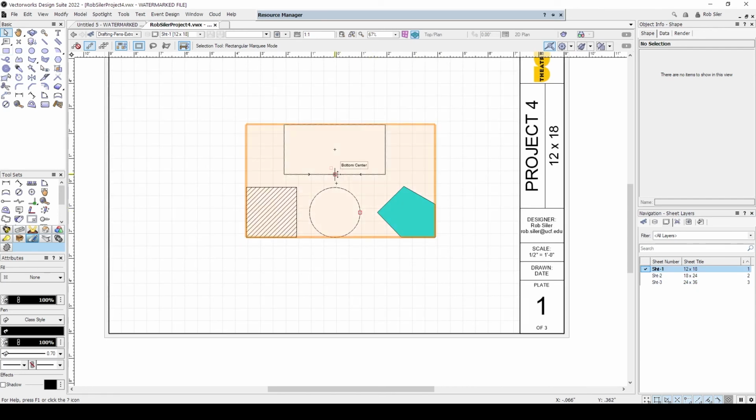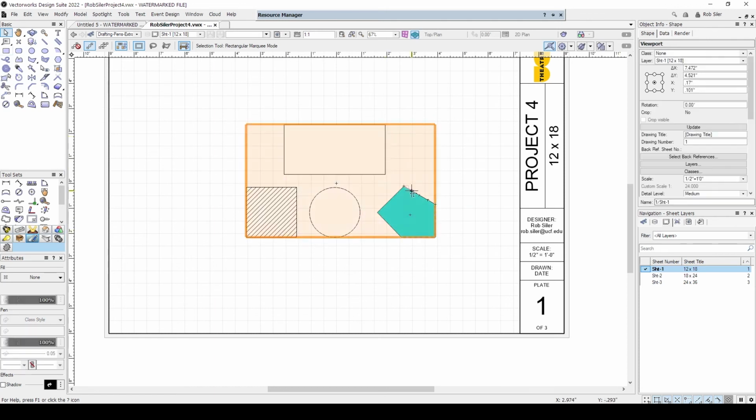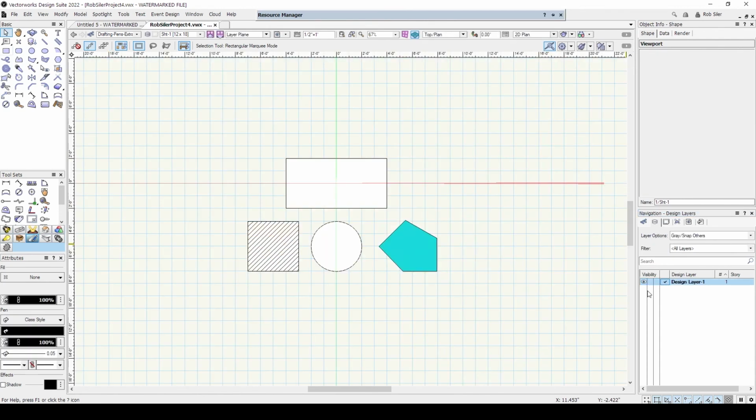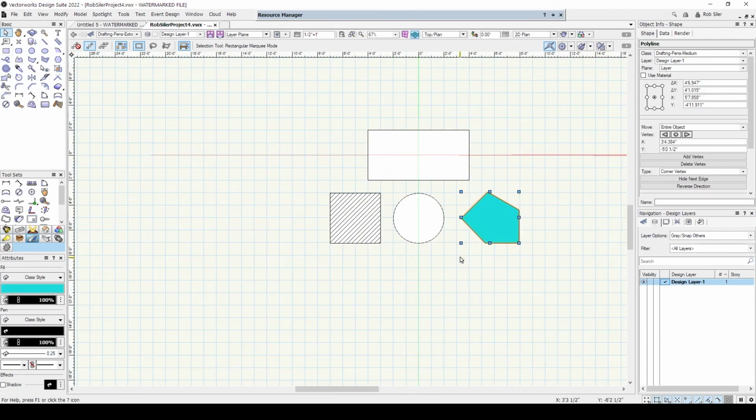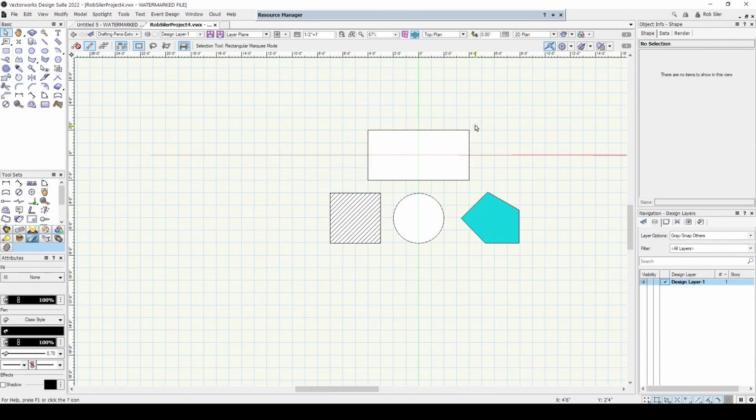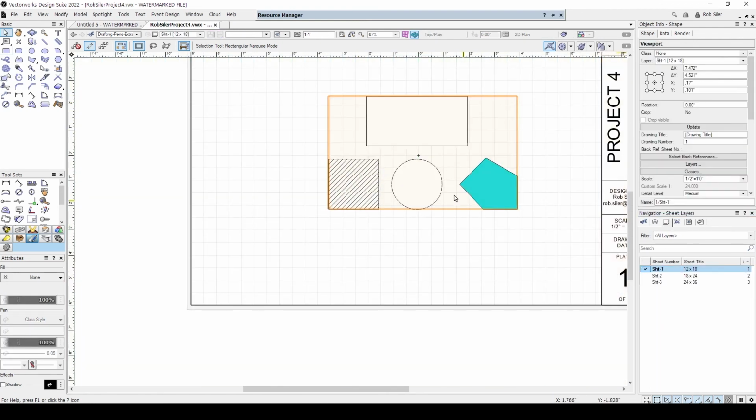And the last thing we're going to do is we're going to dimension these objects. We can do this 2 ways. We can do it in the design layer, which is really helpful for when you're working with lighting fixtures, but it's bad practice when you're working with scenery. The reason being is you may need to use this drawing multiple different times on multiple sheet layers and things like that, and you may not necessarily want your dimensions popping out over top of it.